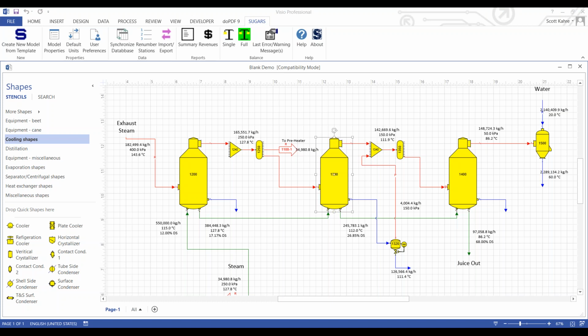No, you can separate evaporator trains into different segments all you want, and that will allow you to put different dissolved solid set points in the different sections. The only thing to keep in mind is that then you need to make sure that you're separately balancing the steam supplying those segments, because they're not going to coordinate their flow of steam from one to the next if they're in separate sections.